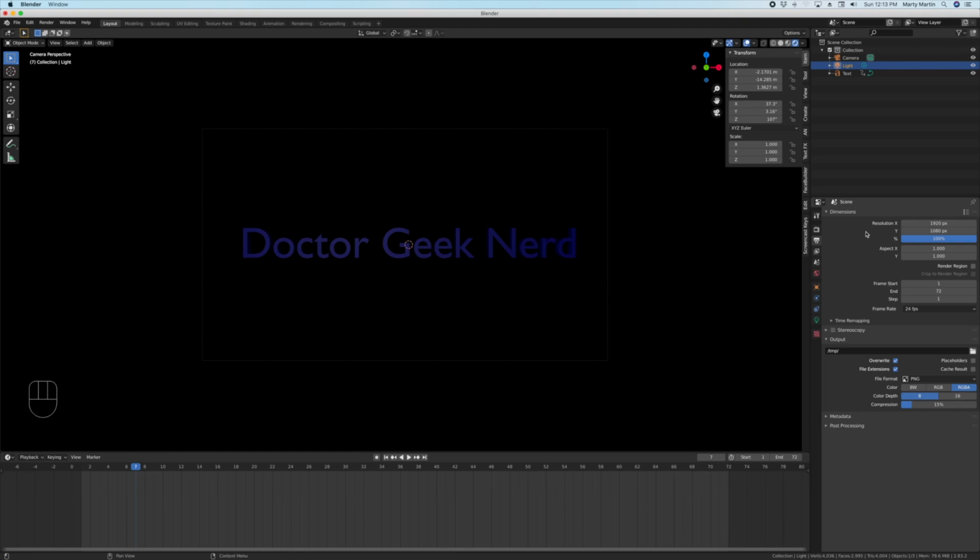I'm going to get the resolution at which the animation is going to render out, and it's set to 24 frames per second. The start frame is going to be 1, end frame is going to be 72, and now I just need to tell it how to output. If I leave the settings where it's at, it will go to a secret folder called temp that's going to be hard to find. So I need to tell it where to save.